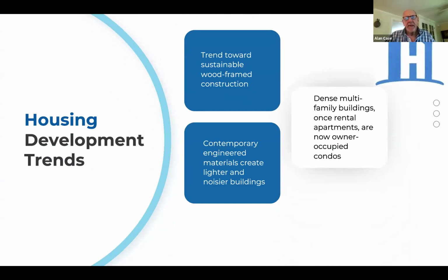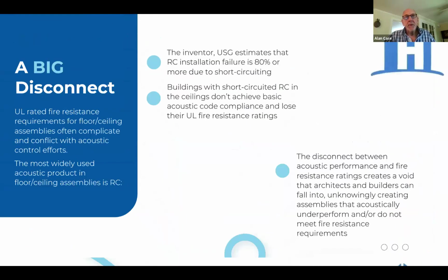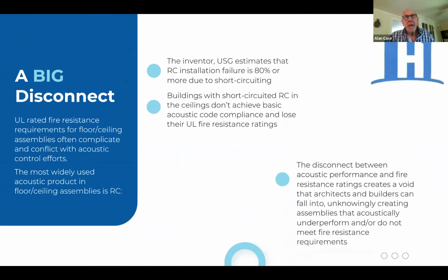If anything is larger than that, and we start with a minimum of 5.5 for acoustics, and it touches the backside of the ceiling membrane, then you have to tighten the spacing of those devices down to the point where on a 12 by 12 foot room, you would have to use 24-inch spacing. You would use 91 devices, and on 16-inch spacing, you would use 130.